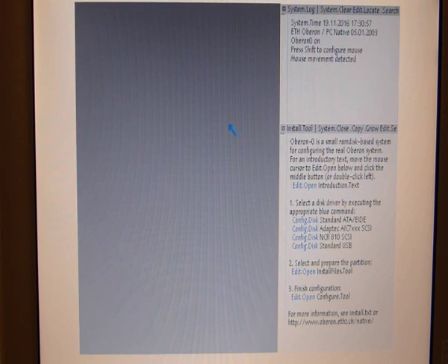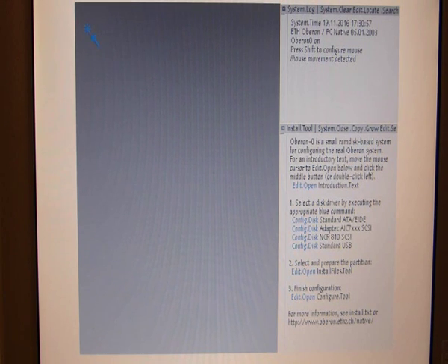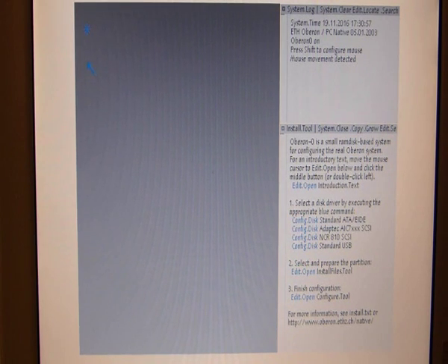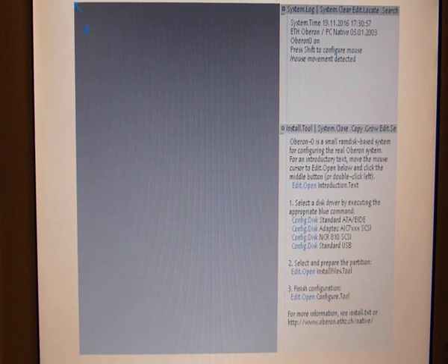When you want to decide for yourself where your viewer will be opened, you can use this pointer and go to the position where you want the viewer to be and press the function key F1. And then you can see a small star marker. This star marker indicates the position where the viewer will be opened when you activate it. Okay, this is a very basic introduction.